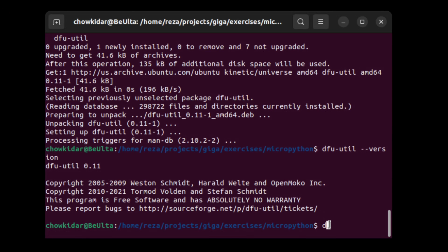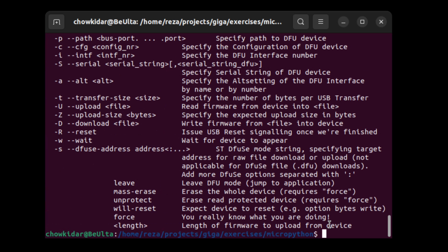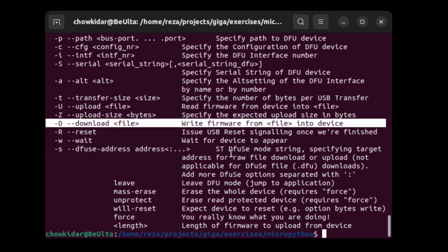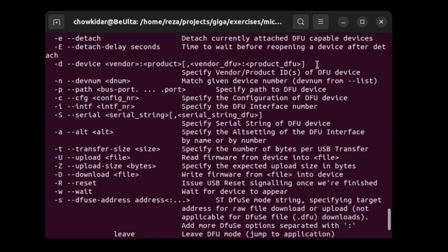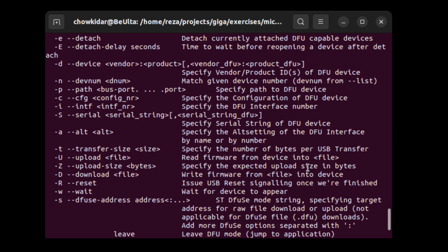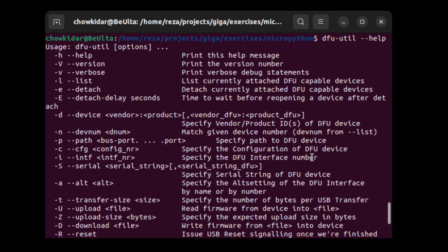After installing the dfu-util utility, check its version number. Invoke the utility and use --version as a parameter as shown in the example to obtain the version number. Use the help option for the utility to obtain a list of all the command line parameters. This information will come in useful later when we flash the firmware.